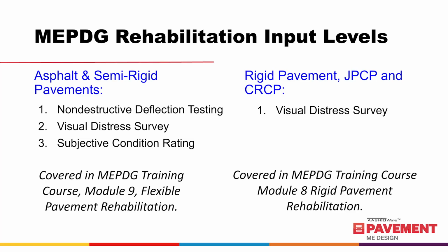For rigid pavements, there is no separate input levels for rehabilitation design. The MEPDG only needs the slab condition and transverse joint load transfer efficiency, which is LTE. However, results from the deflection testing program can be used to supplement the input values to the PMED software for rehabilitation design. Again, this topic is also covered in MEPDG Training Course Module 8, which is Pavement Rehabilitation.